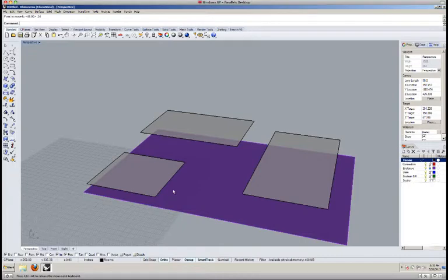What I need to think about now is how these are going to be connected. I can have a series of ramps, or a series of stairs that connect them to each other. The handout gives you parameters for the stairs, which are a minimum of 12 inches deep in terms of the treads, and 6 inches high. And they likely need to be 4 feet wide, so we'll use that as a parameter.